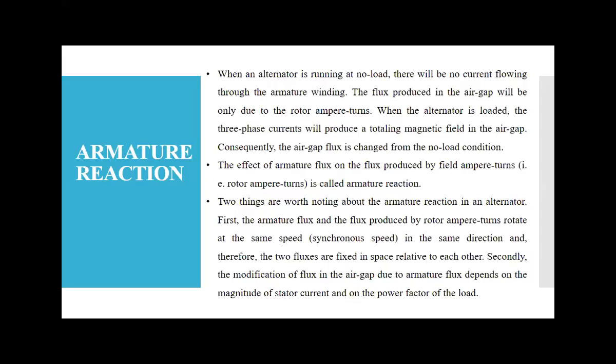In the armature, there are different types of winding we can make. We have three possibilities. Either we use a single layer or a double layer. Then another option is whether you wind concentrated or distributed all over the alternator. The third option is either a full pitch or a short pitch. Generally, our armature is either single layer or double layer.